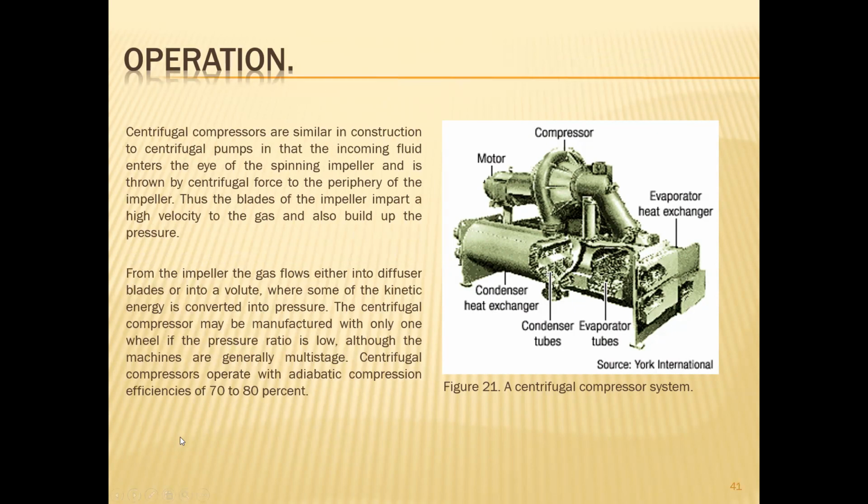Operation. Centrifugal compressors are similar in construction to centrifugal pumps in that the incoming fluid enters the eye of the spinning impeller and is thrown by the centrifugal force to the periphery of the impeller. Thus, the blades of the impeller impart a high energy to the gas and also build up the pressure.